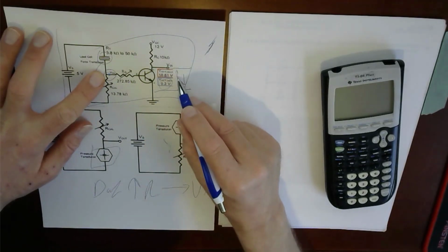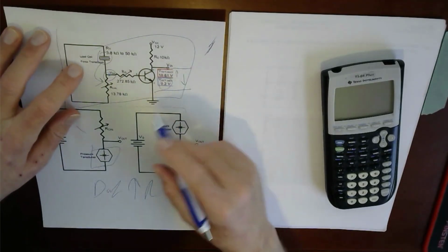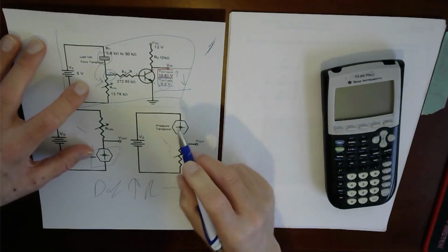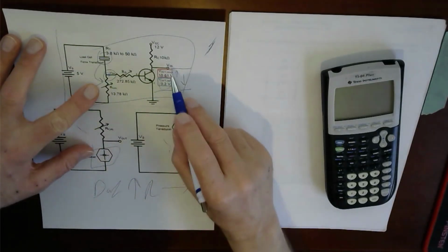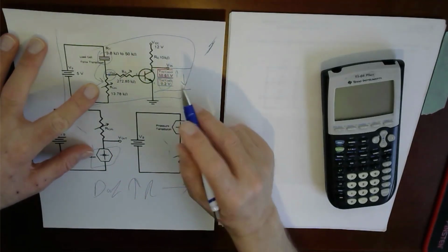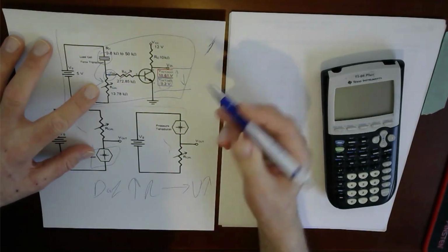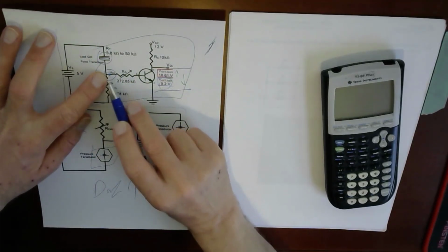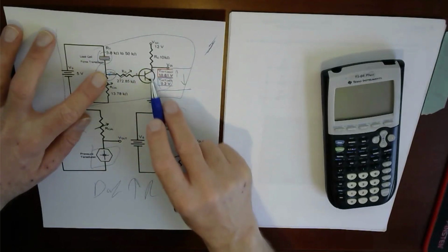The voltage out increases. So I want to make sure my LDR is either here or here, such that when it's at its darkest, this is at its lowest voltage, and when it's at its brightest, that's its highest voltage. When it's darkest, the resistance is highest. I need the highest voltage here when the resistance is highest, so that the highest current can be here, so that it's closed.